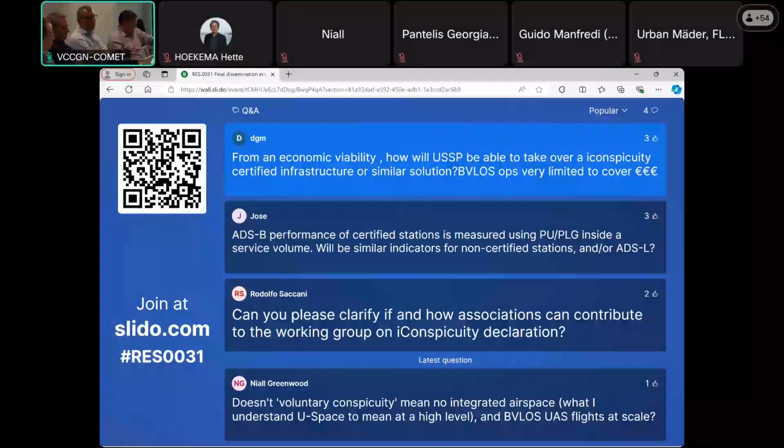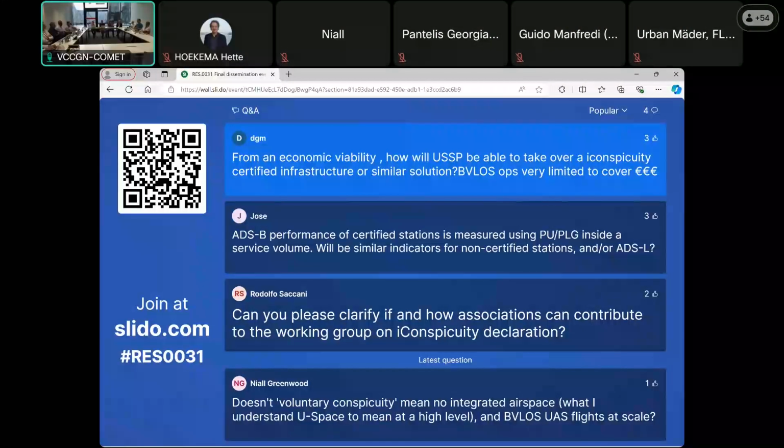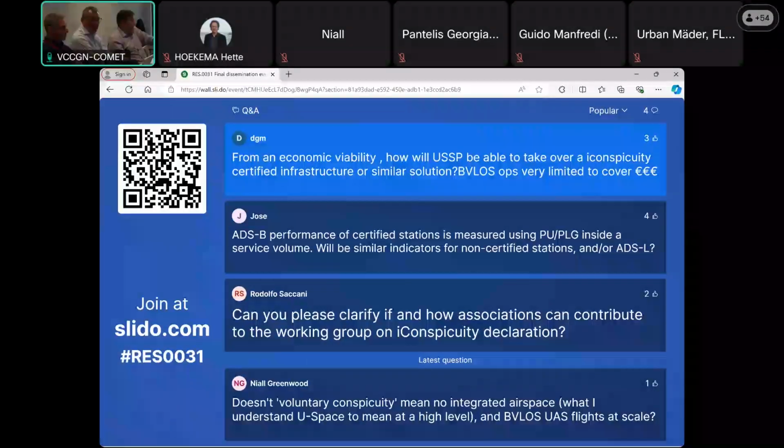Outside of U-space, drone operations beyond visual line of sight can effectively happen only in a low traffic density environment, which in practical terms translates into airspace typically outside of any aerodrome or landing site for manned aviation, lower than probably 500 feet, where typical operations do not take place, and in rural areas, so not urbanized areas.